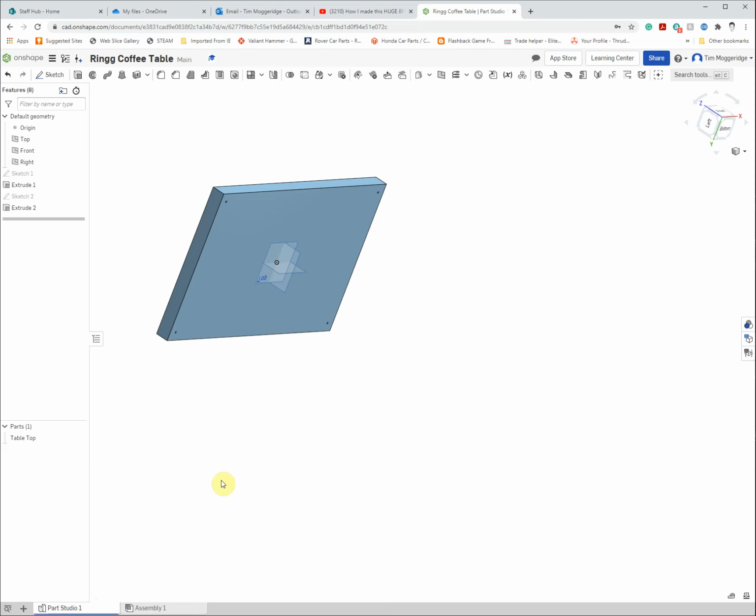And that's really helpful for something we call top-down design, whereby we're modeling the parts as we go along and we're making sure that they fit together by making them in the same model. We're not making lots of individual parts and then trying to assemble them afterwards. So in this instance, we're going to model one of the legs.